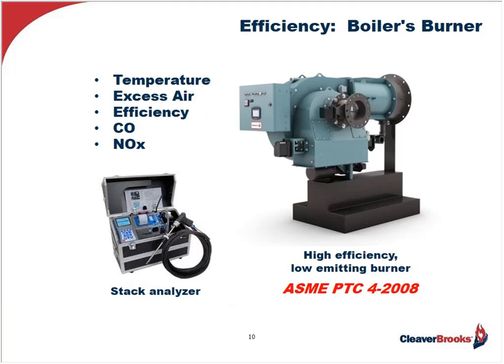Now, determining the fuel to steam efficiency begins with a close look at the burner, its physical condition, and the features, including its turn-down capability, because we need to establish the actual efficiency during various firing rates. And this begins with the use of a good stack gas analyzer, which registers what you see on the screen now: temperature, excess air, efficiency, carbon monoxide, and possibly NOx, though this does not affect efficiency per se. But many analyzers include this feature because of the emission laws enforced today in various locations throughout the country, as I mentioned.